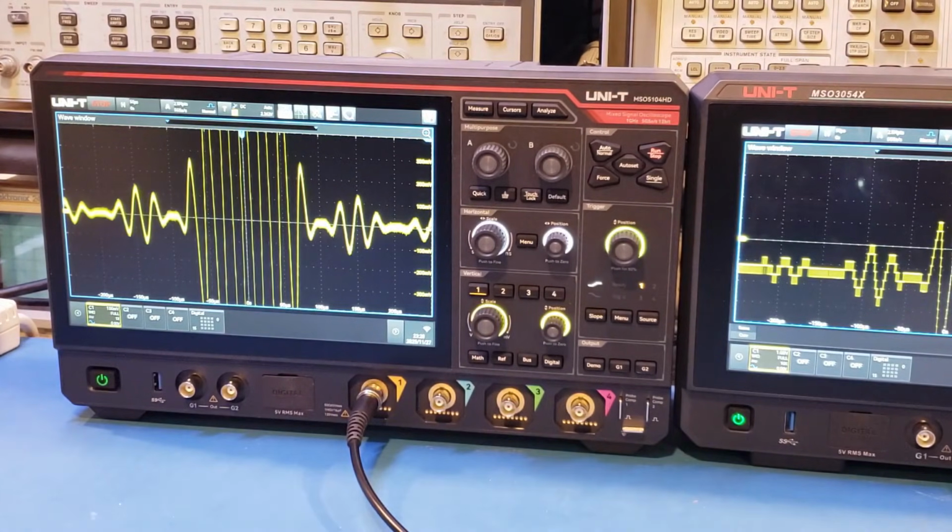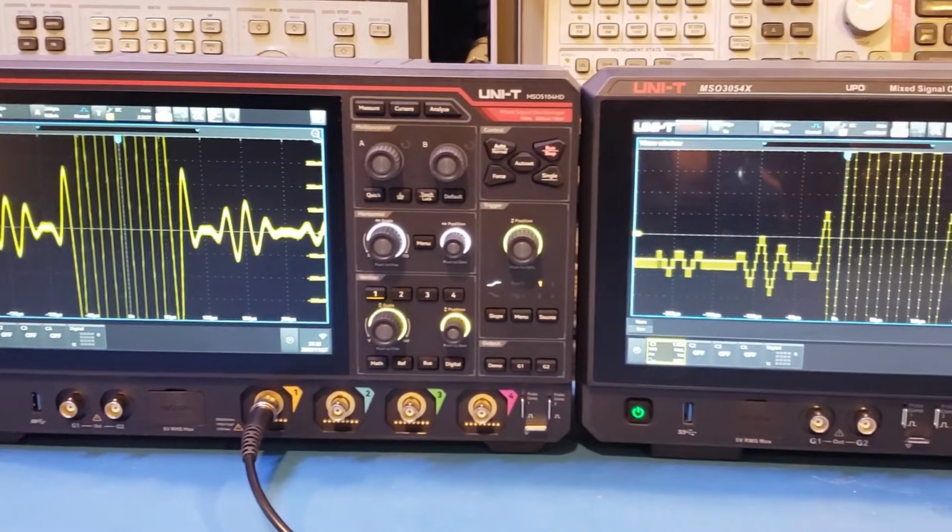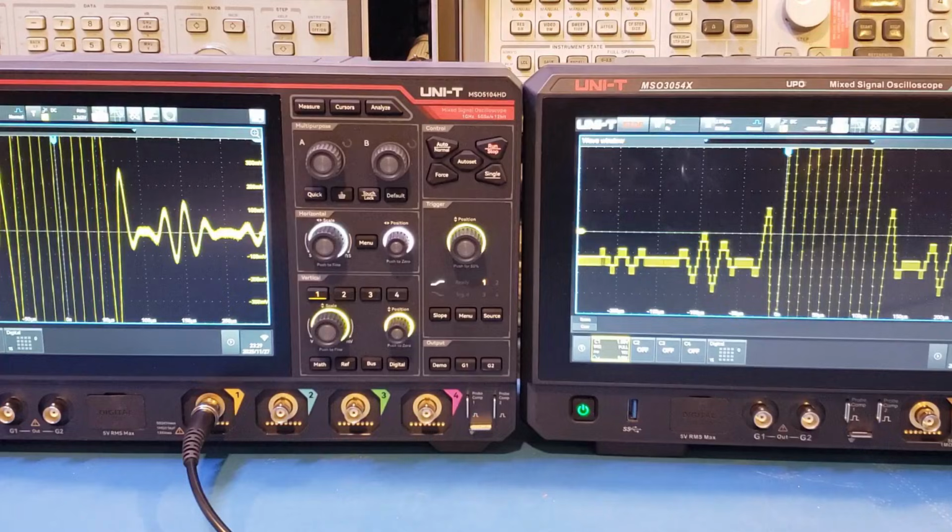So you can see when we adjusted the vertical amplification, the signal actually appears a lot cleaner on the scope compared to that on the MSO3054X. And that is because for a 12-bit oscilloscope, you have extra 4 bits. Essentially, we'll have 16 times finer granularity. So for the same capture signal, we can actually zoom in further and still have good resolution, as you can see here. So now with the same captured signal, you can actually resolve both the higher amplitude portion and the lower amplitude portion in the same shot. This is essentially the higher dynamic range I mentioned earlier.